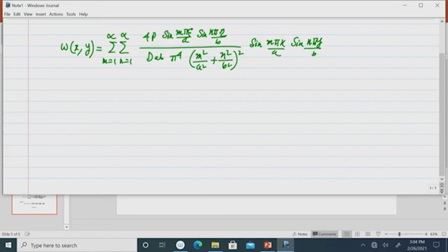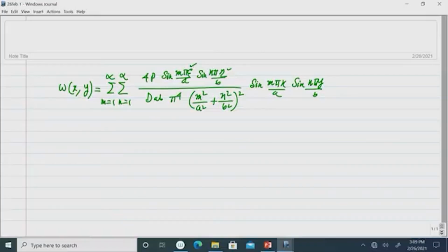So, we have derived the expression for the deflection surface of the rectangular plate simply supported along all edges subjected to a concentrated load. The location of the concentrated load is defined by two variables, xi and eta. In a plate actually there may be a number of concentrated loads. For example, a deck panel of a bridge subjected to vehicle loading. There may be two axles in general, so on both sides, right and left, you will get the wheels. So, wheel loads are imposed, and if this is say P 1 in the same axle, of course the load is the same, then P 2, P 2. If this is the direction of motion, you will see that the load imposed on the plate is a concentrated load and it is a moving load. So, concentrated load formulation is very important especially for bridge deck analysis, when the wheel loads are treated as concentrated loads.